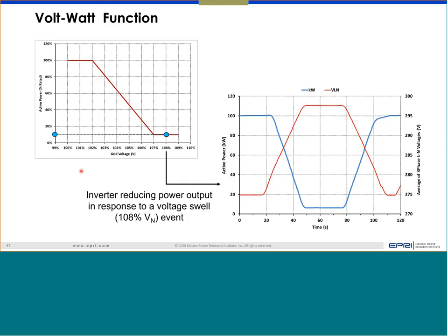On the other hand, volt-watt might be. So yes, depending on the X/R ratio, volt-watt could be more effective, but at the same time you have to remember that it will directly impact the kilowatt-hour generation, which is the revenue. So unless you have some sort of agreement with the customer, with a very aggressive volt-watt you may get some pushback.